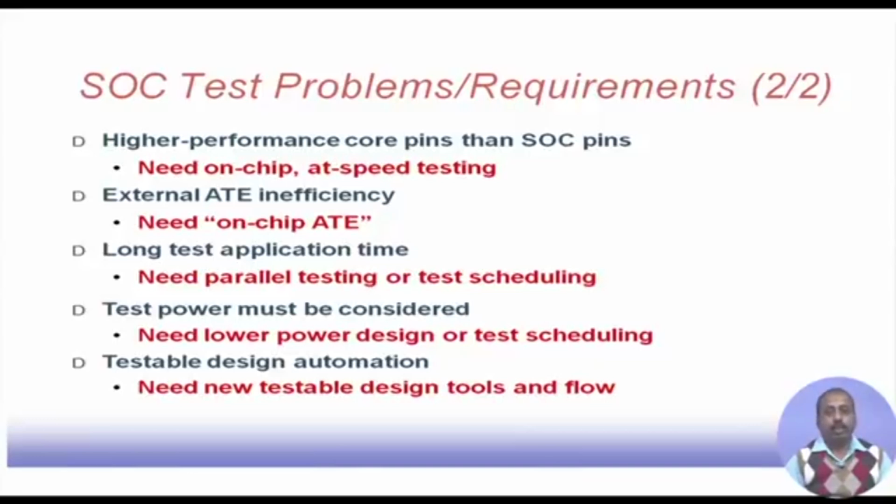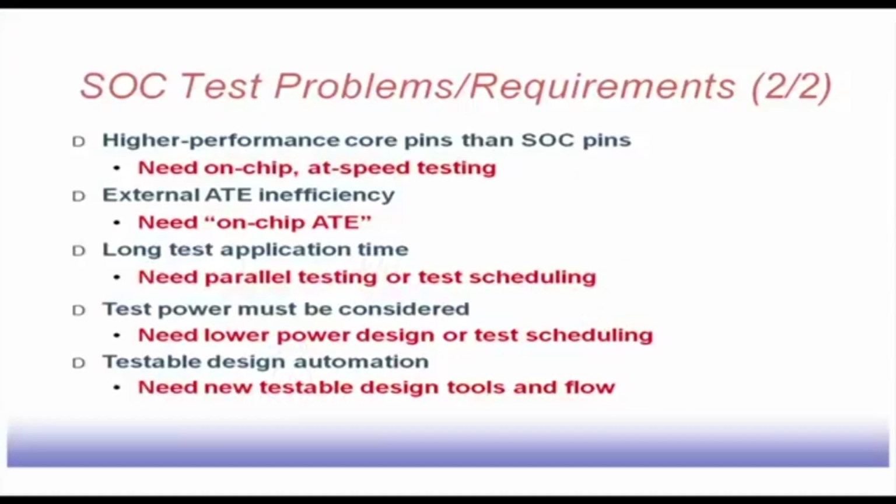Now, for a new design in my company, maybe I am doing a design at a high frequency, but the existing ATE is operating at a low frequency. So, I have to somehow test this chip with the available low frequency ATE, because ATE equipments are very costly. So, I cannot go for a new ATE just to test this new chip. So, there must be some mechanism by which I can use this low speed, or inefficient in that sense, ATE to do the testing of these high frequency chips, or in some sense we can say we need some sort of on-chip ATE. So, that is a very desirable situation, but it is very difficult to have. So, on-chip ATE is difficult.